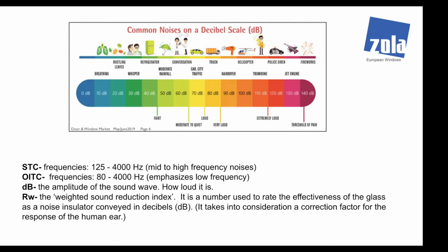So if you have an exterior situation with helicopters, and I'll point to this graph here at the top, that's 100 decibels, and you need to maintain a 43 decibel interior environment, then you have a situation where you have to reduce by 57 decibels. So all of the wall, the window, and every single component has to meet a minimum of 57 decibel RW, a weighted reduction index of 57 decibels. That's quite large. So hopefully you're not building it adjacent to a helicopter landing pad.